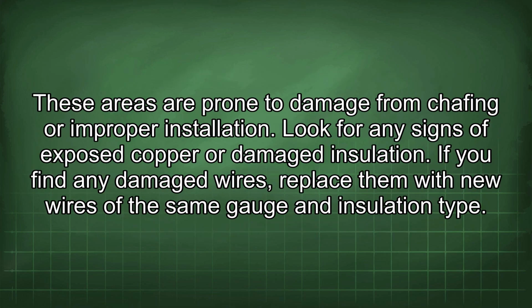These areas are prone to damage from chafing or improper installation. Look for any signs of exposed copper or damaged insulation. If you find any damaged wires, replace them with new wires of the same gauge and insulation type.